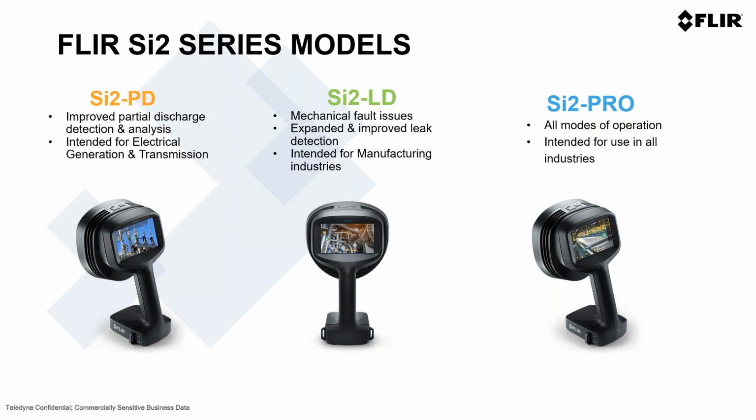Then the SI2LD unit has leak detection for compressed gases, with a list of gases that allows us to give the quantification on screen of the leak size of the gas. Good to remind here that this camera works for any kind of pressurized gas detection. So even if it's not listed in our gas specs, the camera will find the leaks anyway, but we will not give calculations on the screen of the leak size and the leak cost, of course.